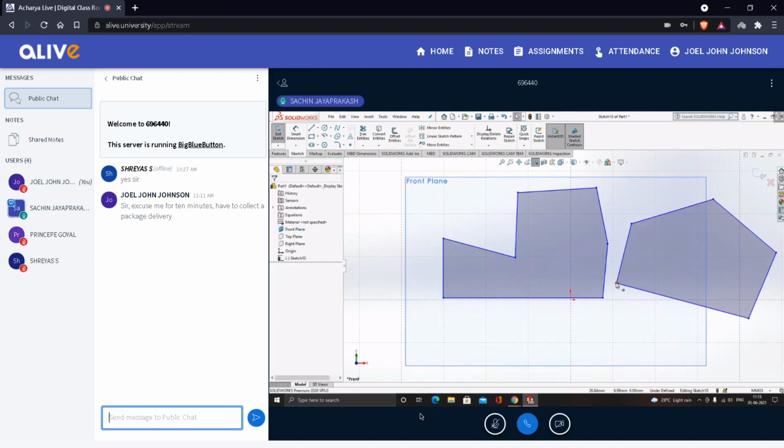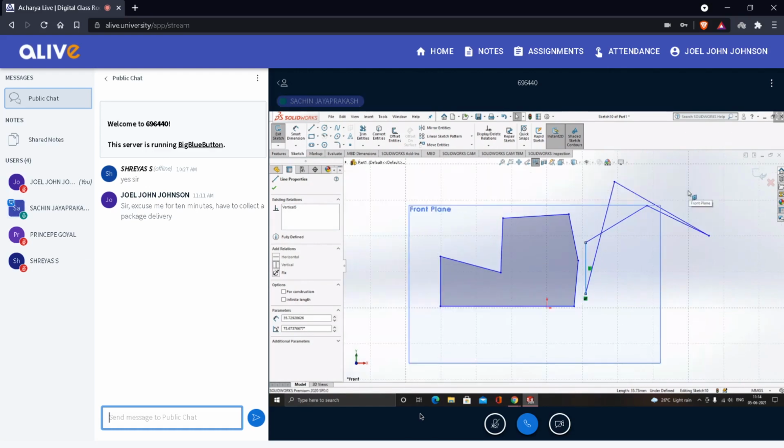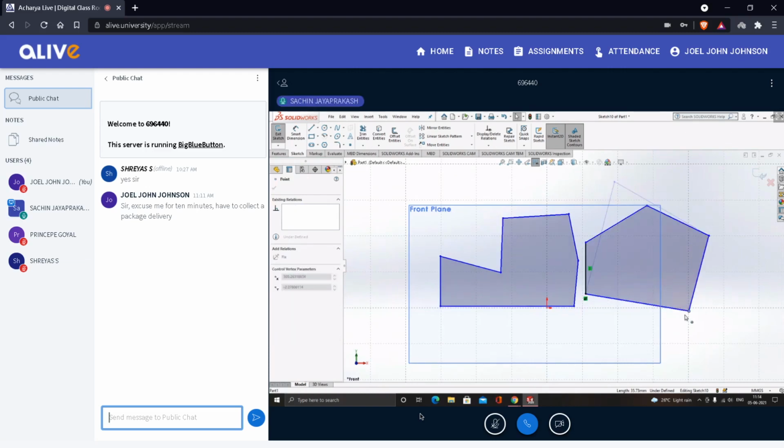Okay, and like last time in CATIA when we were doing constraints, we were fixing one point, right, so that it doesn't move. So here also we can do the same thing. Now this particular point is selected, fix it. So now that fixed constraint is set. So this particular point I can't move anywhere on the screen. Okay. Now I can select this. I can do horizontal, or I can do vertical like this. So based on this, as we have relation between the other things also, so this changes. This we can adjust it later.